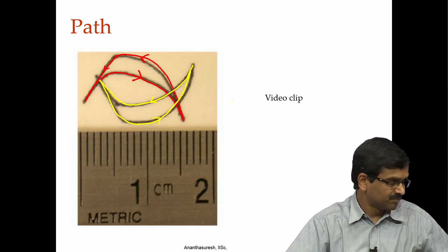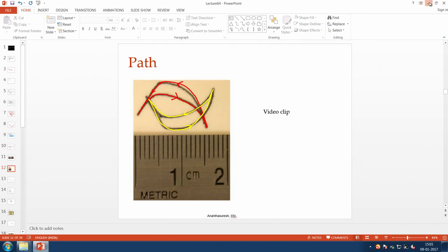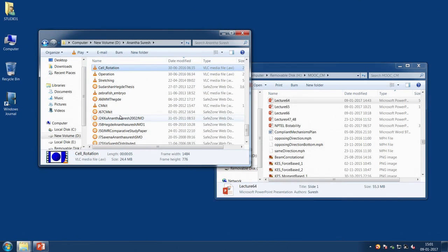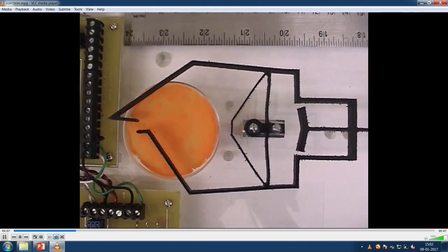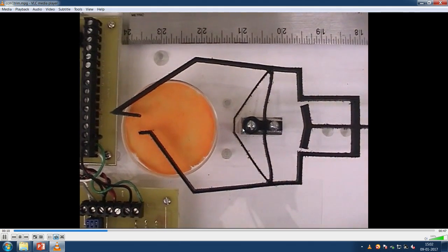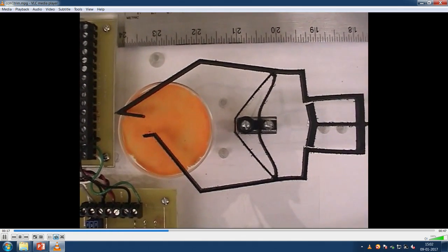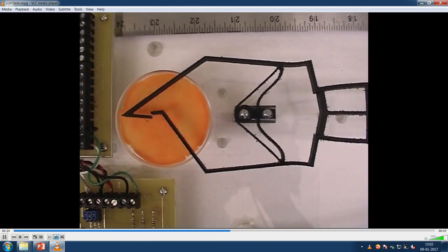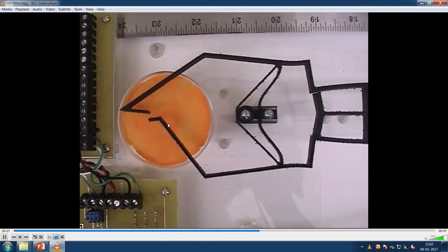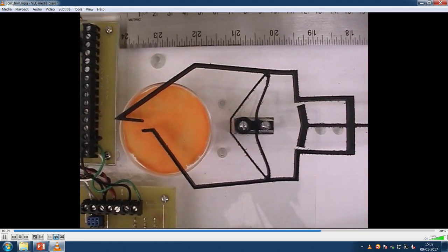Let us watch a video clip of this mechanism to understand what is happening here. Let us just see the video. Yeah, here is the device, of course left and right switched, and you can see where the contact, where the arrow is. When that contact happens there, this non-smooth behavior begins, and then soon after these contacts also take place over here and they change their path. So, you have to focus on where the 2 pins are, they are tracing this complicated path, now going back, and then whenever the contact is lost, suddenly these things will change their direction.